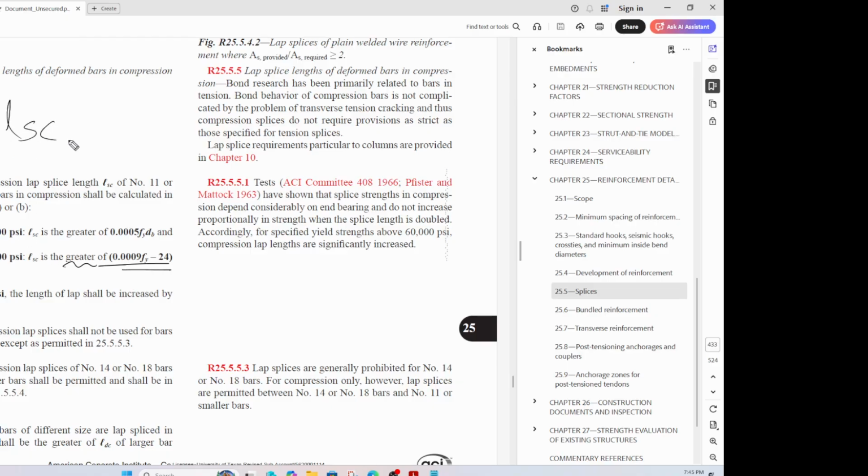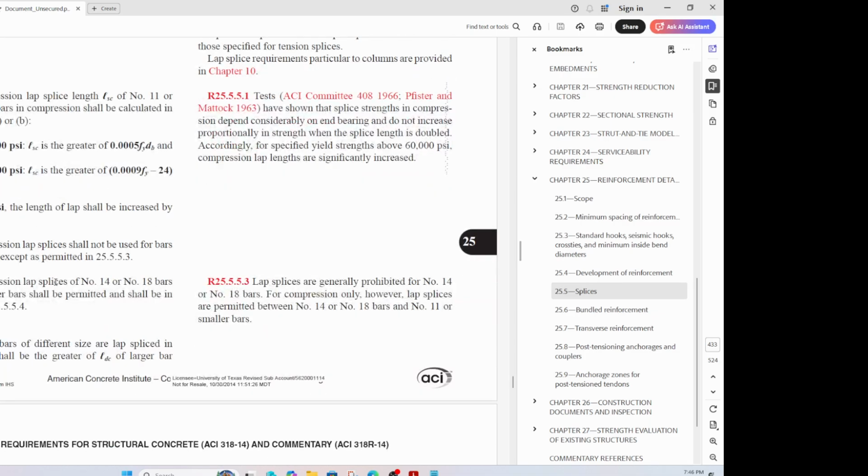If your concrete is less than 3000 psi, then you have to increase the splice length by one-third. So that's another rule there. When you look at a section like this, you're not just worried about one portion of it, but you will have to broaden the window till it overlaps the next section. That's when you pick up information like this. Maybe in your question, the concrete is less than 3000 psi, and you need to do this, but you also need to do that. So there are certain rules.